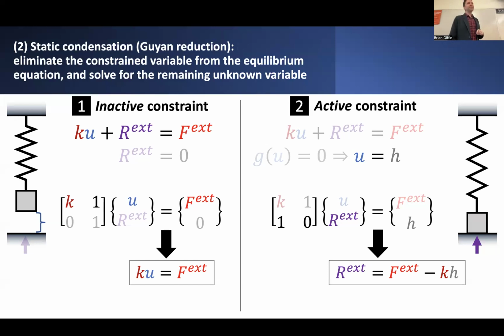And if we do that, then effectively we're saying, well, maybe let's make it such that the block, once it comes into contact with the surface, maybe it can displace down just a little bit more. Almost like we're not treating this bottom surface as a strictly rigid surface, but such that we have maybe a little bit of elastic behavior in this surface.